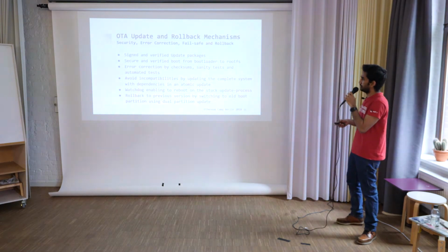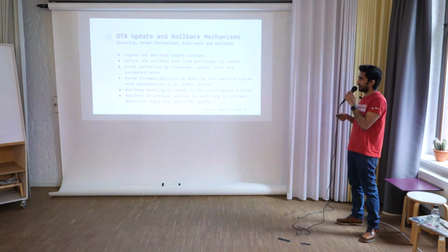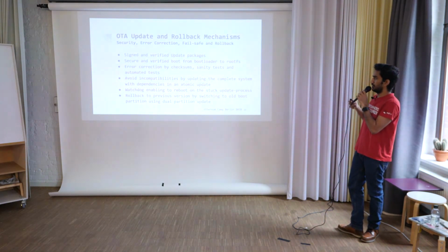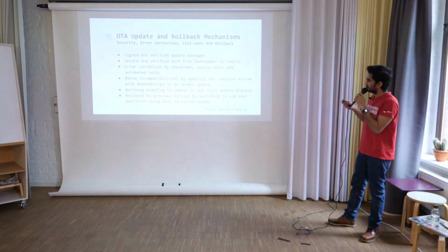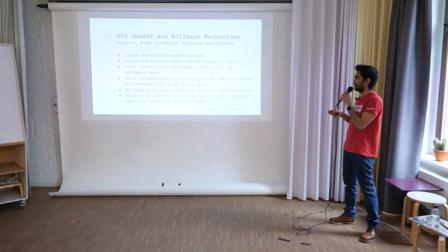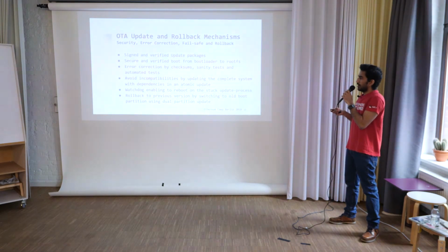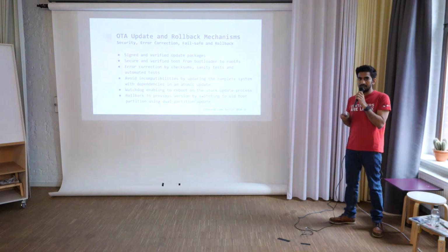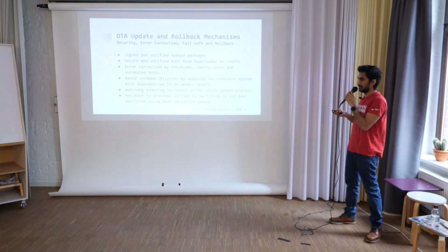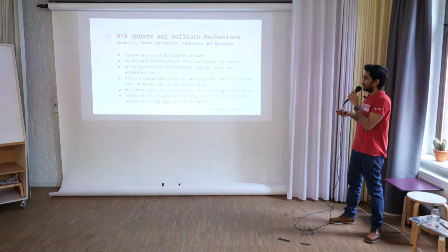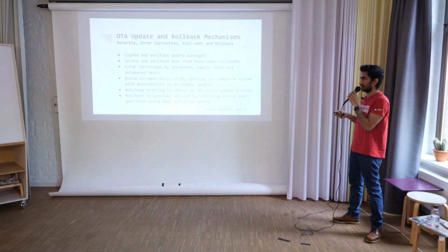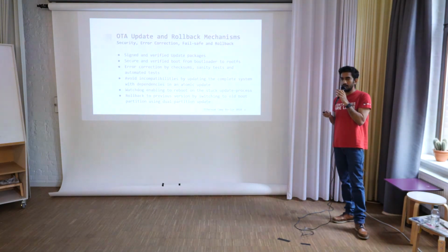Basically, these are the parameters or facts people look into for an OTA solution when they want to evaluate something. Usually, all of them provide signed and verified update packages. There is secure and verified boot from the bootloader, so that your images are verified at every stage, and usually error correction, sanity tests, and checksums. Atomic update provides this: you get the whole image, so that you don't have incompatibilities between your updates.